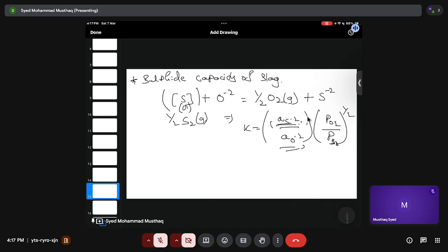They do not have good electrical conductivity, and the same goes for thermal conductivity, because your electrons are not free, and most of the conduction of heat in alloys happens through electrons. There are phonons, which are nothing but collective oscillation of atoms. Phonon movement is sluggish compared to electron movement, because electrons are tiny and can move very fast. So most of your thermal energy is carried by your electrons, not by your phonons.